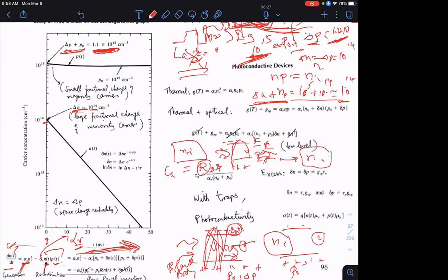Now, going back to my expression for the recombination rate, which is alpha R times number of electrons times number of holes, what do you think will be the recombination rate? It will be alpha R times the number of electrons times number of holes in equilibrium now. And what is that equal to?